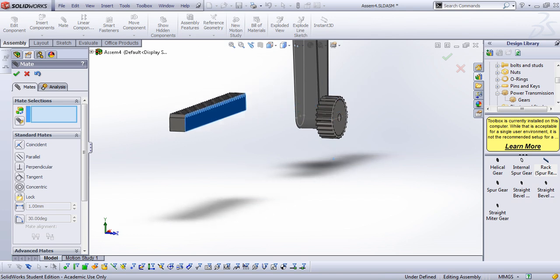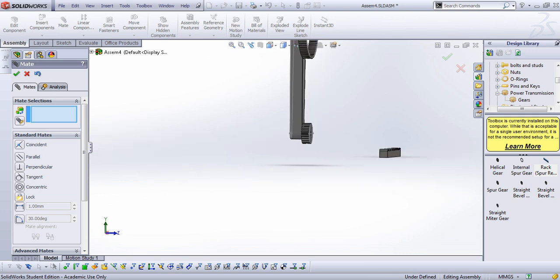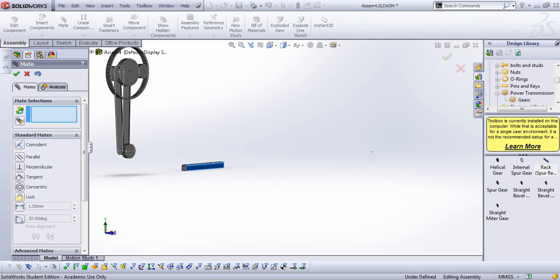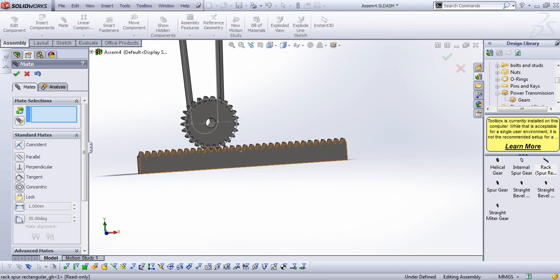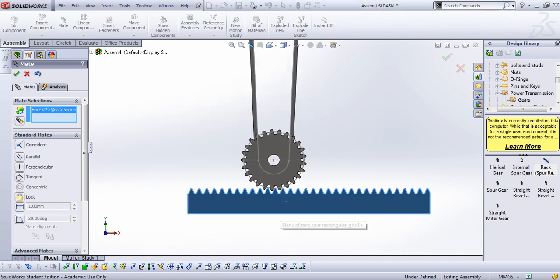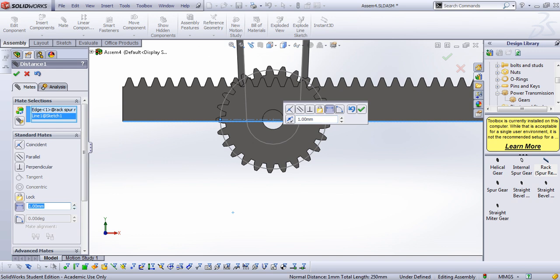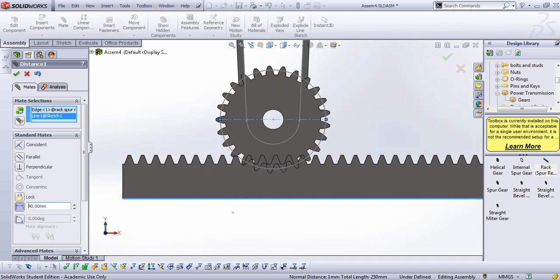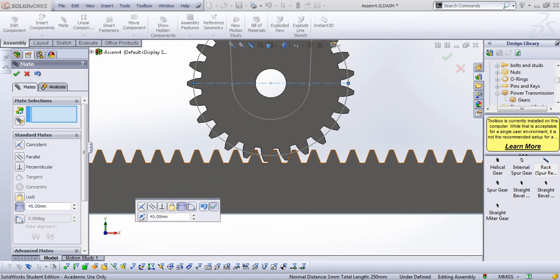Yeah, this is good. Actually, I think it's kind of an illusion, because now you can see that you can't even move it here. It's still in the same position. Even previously it was working there, because by changing it, you move it in one plane only. Okay, let's go to this plane and get them close to each other. In that case, let me use a simple distance, and I select this and this line again, and the distance here 40. Let's see, 40 works. A little more, 45. So you have to place it in the right position. Yeah, here is good. Make it 45.